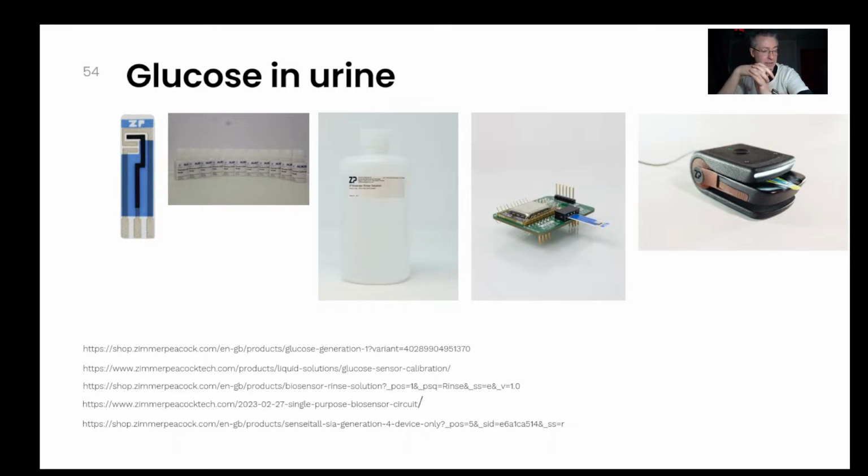Biosensors, unlike other sensors, the sensor is in intimate contact with the sample. If it's a temperature sensor, there's a temperature sensitive element sitting behind some material, so it's quite shielded from the sample. With biosensors, it's not the case. We're actually in the sample. So the sample, in your particular case, will be the biggest source of inaccuracy because of its irreproducibility, more than the actual sensor itself. Can people do the measurement of glucose in urine? Of course you can. You can get glucose strips. But just don't think that with one of our glucose sensors, you can just put it in urine and you'll get accuracy.